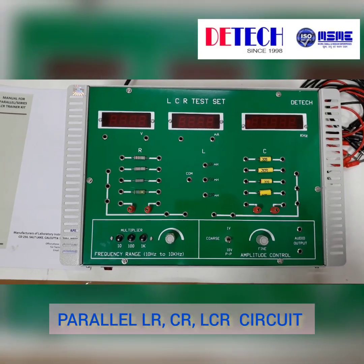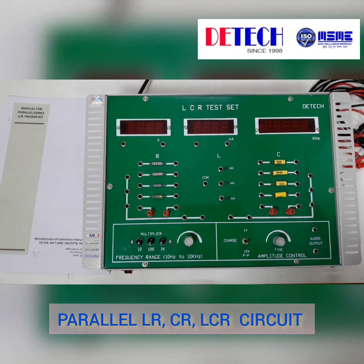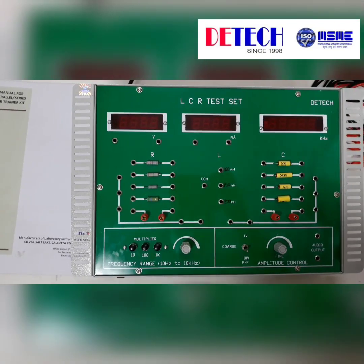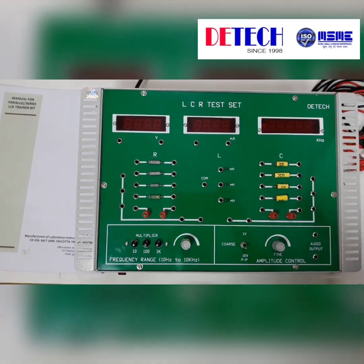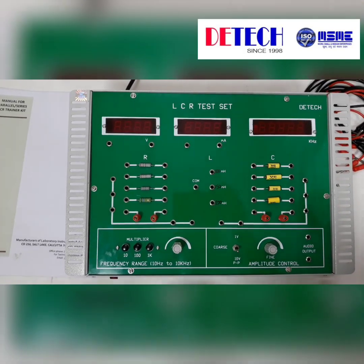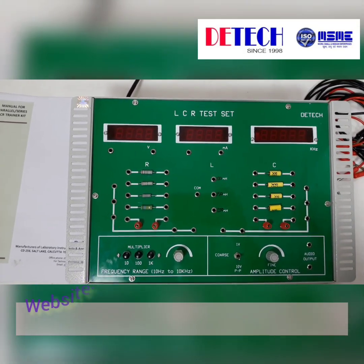This is our setup for finding the resonant frequency using a parallel LCR circuit by drawing the frequency response curve. This is a self-sufficient kit which comes with an audio oscillator having a frequency range of 10 kilohertz. There is an amplitude control, and the amplitude can be varied from 0 to 10 volt peak to peak.